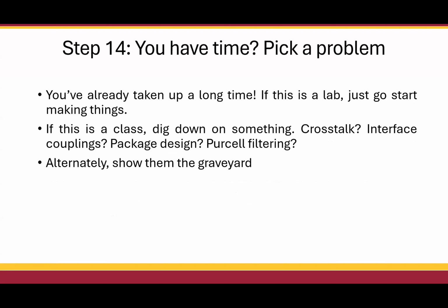I prefer Purcell filtering at this point, because I think the one thing that we really don't get enough of is classical microwave engineering. And Purcell filtering is really, really addressed best with classical microwave techniques, just looking at impedances and admittances. And so you can just dig down into that and show them how a bunch of different Purcell filters work, and show them all the counterintuitive results you get from Purcell filters, like how sticking a Purcell filter in front of something can make the resonator suddenly extremely broadband, that kind of thing.